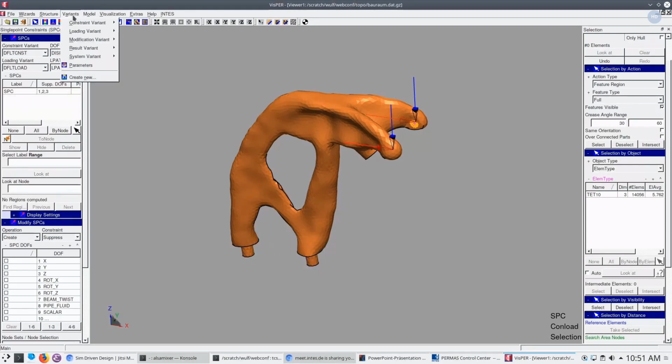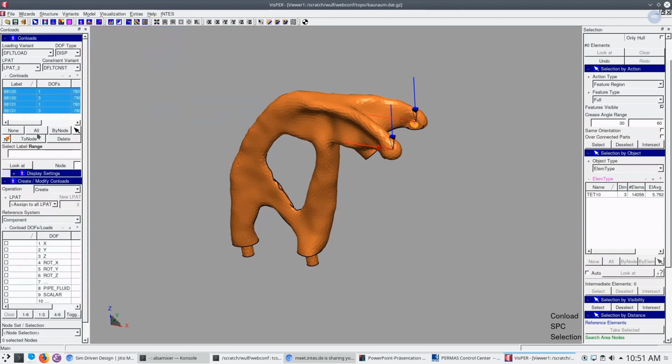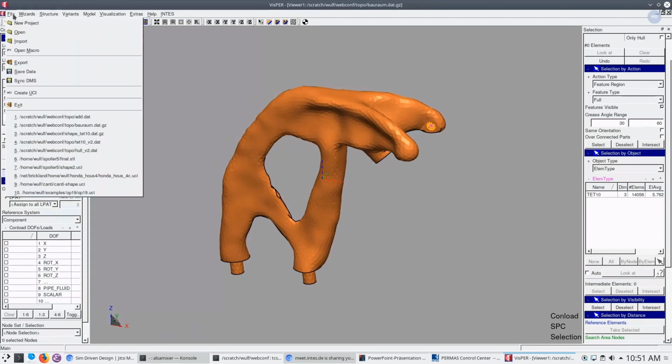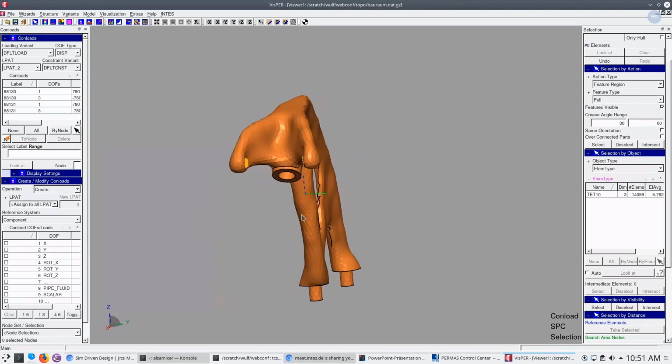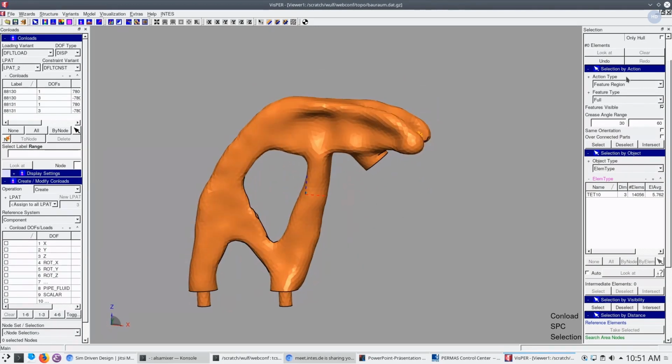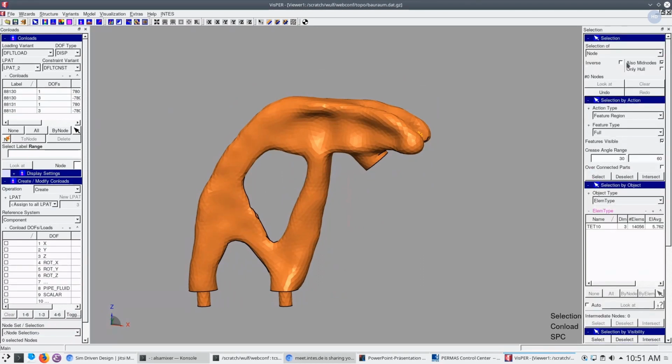What I should do initially is have a look at the stresses, just to know about the stress level. Let's remove this. Okay, and then what I have to do is define an area where I want to optimize the shape. This is maybe the only time where the user has to take some care, that he carefully chooses a node set that defines the area where we want to change the shape, and also where we want to control or examine the stresses.